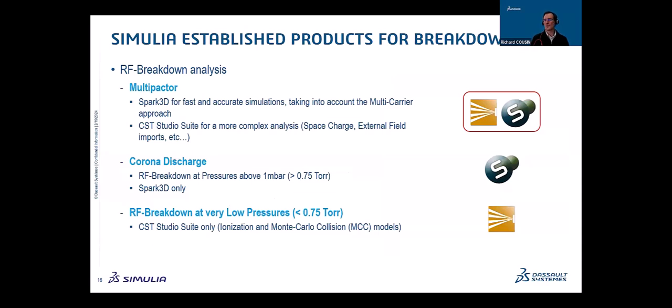Then I would like to provide you with some information about the tools and the established products that we have for RF breakdown. You have, as I said, the multipactor analysis, which can be performed using Spark 3D for fast and accurate simulations, taking into account the multi-carrier approach. So you can use these tools directly in the same way as Carlos mentioned yesterday, for those who were in the filter session.